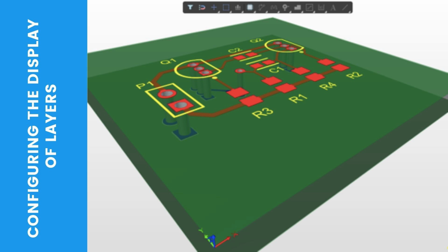You design the board looking down into this stack of layers, placing components on the top and bottom sides of the board, such as top layer or bottom layer, and other design objects on the copper, overlay, mask, and mechanical layers as you build up the design. As well as the layers used to fabricate the board, which include signal, power plane, mask, and silkscreen layers, the PCB editor also supports numerous other non-electrical layers. The layers are often grouped in the following way.